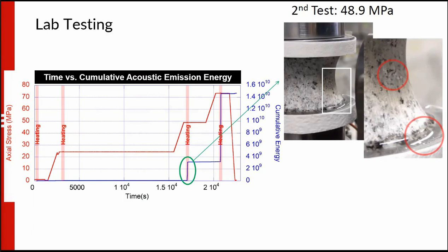So what this result shows is that the first two times he heated, you didn't see anything break, but then the third and fourth time, when there was more stress, you saw this signal of rock failure. So this tells us that this thermal heating and thermal stress does help to induce breakouts where it didn't used to exist. And the onset of this occurrence of breakout is actually a function of the far field stress that's applied to this rock.